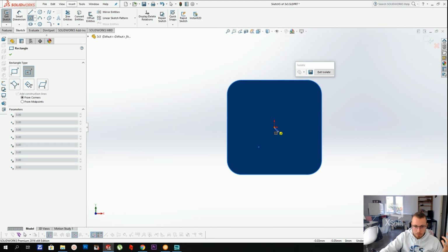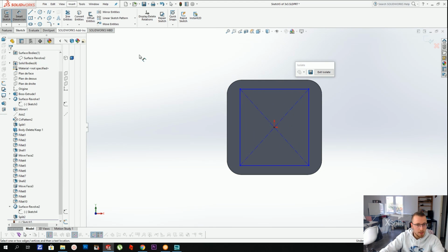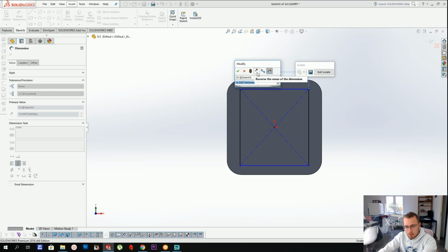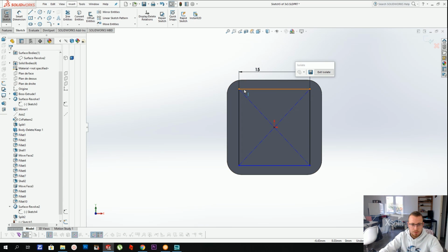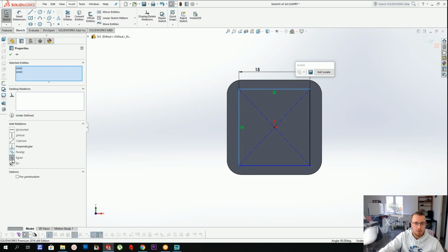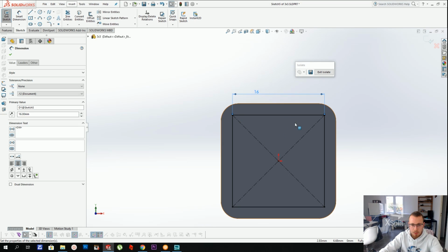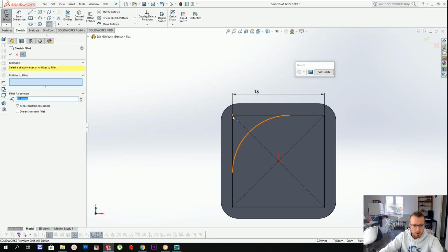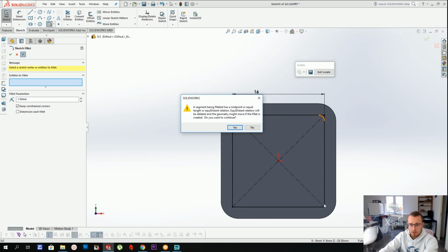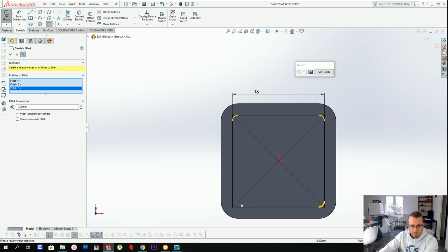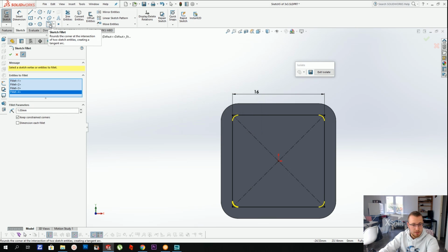It's not really important what that part looks like. I'm just going to create really any sort of shape. It doesn't really matter. Here I'm making a square that's 16 millimeters wide with, let's say, 1 millimeter fillets. It really doesn't matter, honestly. And you can add fillets inside a sketch. It's called a sketch fillet, so the name is pretty straightforward. And then you press OK.